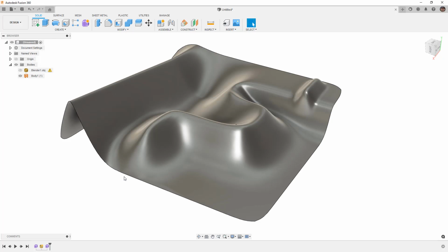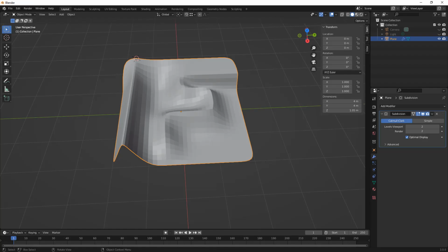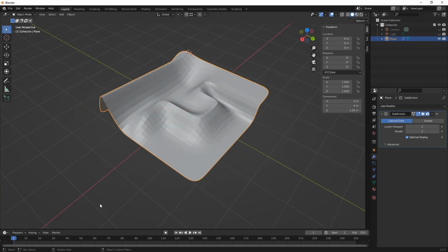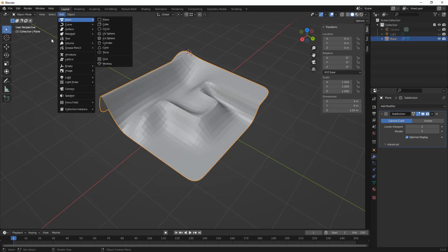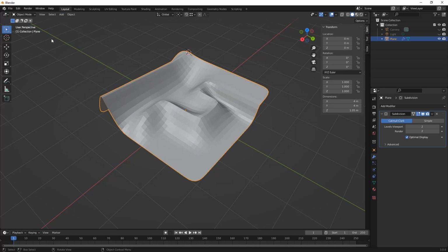body. Now, we could continue to play around with this as much as we want, but I really don't think that it's very beneficial. So at this point, the important things that I want to make sure that we understand in Blender are going to be the ways in which we can add objects, the ways in which we can make our selections a bit easier by using Alt on the keyboard or Option if you're on a Mac, and by using Control or Command if you're on a Mac.